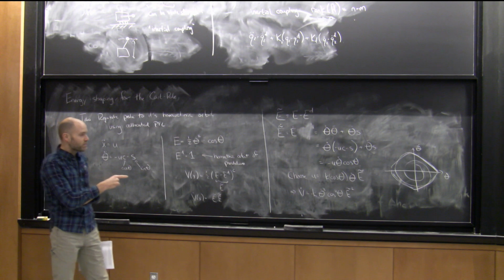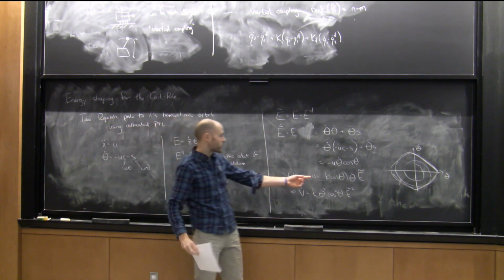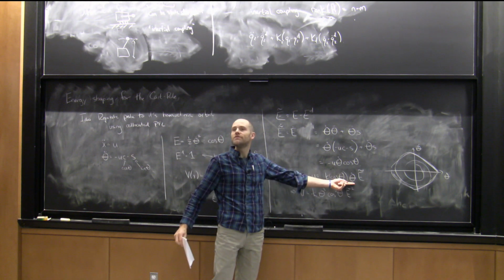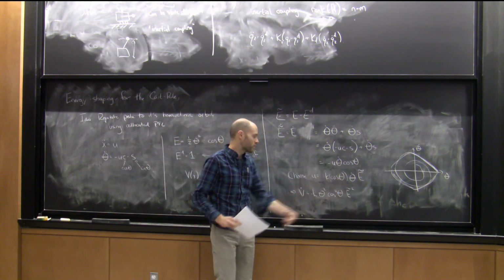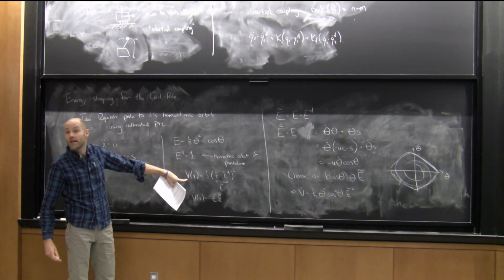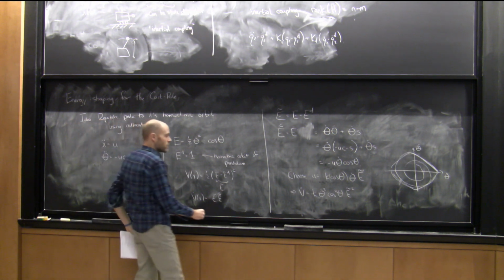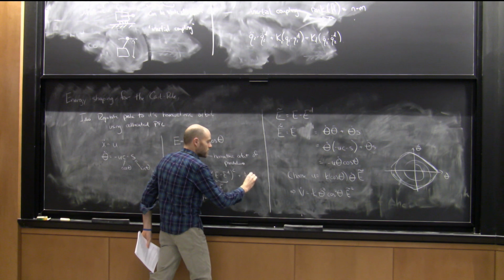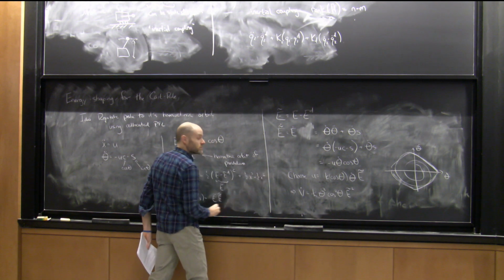This actually doesn't complete the job, because when I run this controller through, X double dot is doing this, okay? So the full story, which I did more carefully in the notes, is you'd actually like to add a few terms into the Lyapunov function which regulates the cart at the same time. So you can tack on 1/2 x squared plus 1/2 x dot squared.